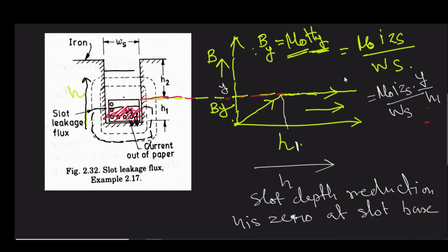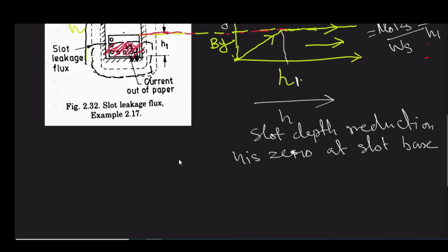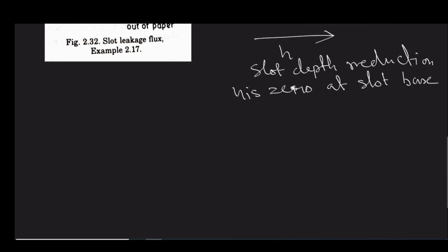Many of you didn't answer. Obviously the transformer secondary and primary windings experience a higher amount of force when you load the transformer, but as the transformer is not moving, those forces or torques on the coil cannot create that kind of complexity or adverse condition. But in a rotating machine they can.